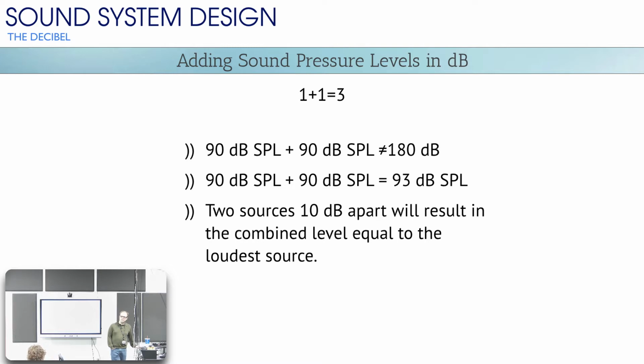Right? If one loudspeaker does not make enough sound, 2 loudspeakers is not going to make enough sound, to make a noticeable difference. So in that scenario, 1 loudspeaker is not making enough sound. Let's say you were 12 dB too quiet. You need 12 dB more sound. So you have your 1 loudspeaker. You say, oh, we need another speaker. It's too quiet. Get another one. Okay, you're now only 3 dB louder, right? Still not at the 12.